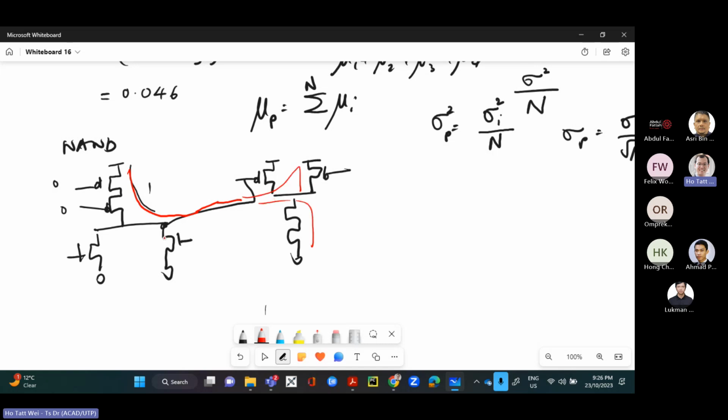and I might, depending on the gate, I might be going through 2 transistors here, or I might be going through 1 transistor here. So what I'm saying is that when you connect up many of these gates, okay, you have many possible logic, right? You may actually be logic 1, going to logic 1. So you go through 2 transistors, 1 transistor, 2 transistors here, or 1 transistor. So it's possible for you to actually pass through 2 transistors or 1 transistor, okay? So if you have 16 pass, the most number of transistors you pass through is 16 times 2, 2 transistors. And the least number of transistors you pass through is 16. But you're not quite sure how many transistors you pass through.